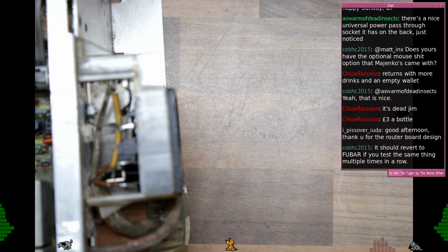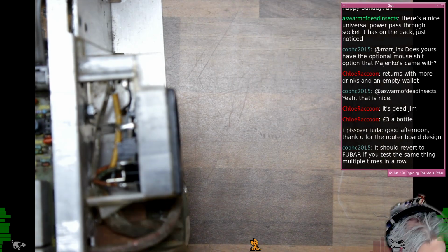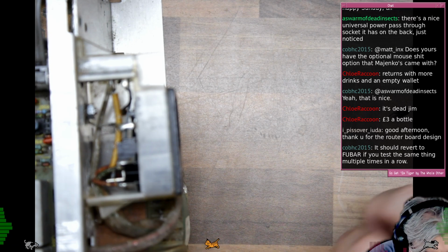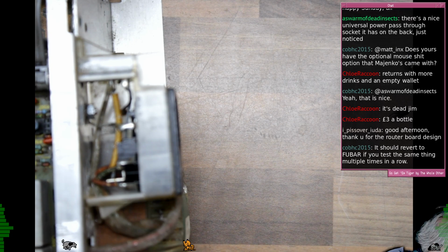The important thing really is partially the transistor itself being the right type, as in it needs to be a nice high frequency one. The main thing is getting the pin out of the pins correct, because this transistor uses a different pin out to most commonly available transistors.